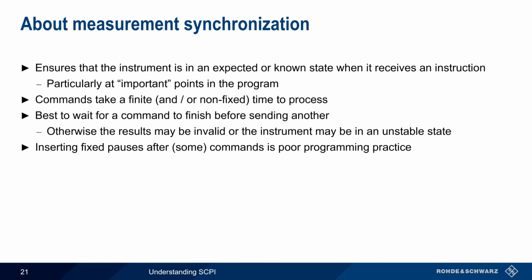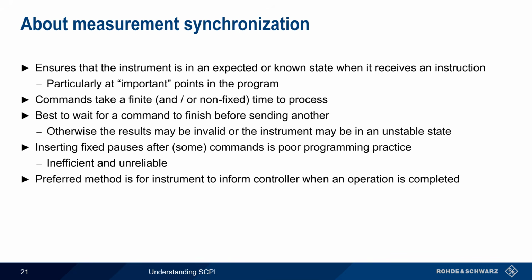One solution is inserting fixed delays in the program, but this is poor programming practice, since it's both unreliable and inefficient. The preferred or recommended method for achieving synchronization is to have the instrument explicitly inform the controller when an operation is completed.